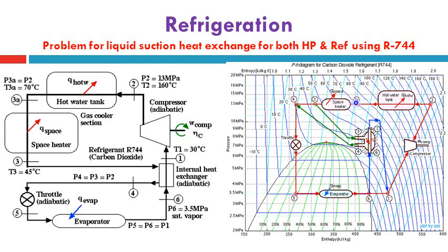In the winter cycle air conditioning system, we can use this amount of heat starting from here to here, 0.3823, and finally the necessary liquid suction heat exchange, which may increase the delta H of the enthalpy here, which will be gained in the air conditioning load, which is requested in the final item of this problem.